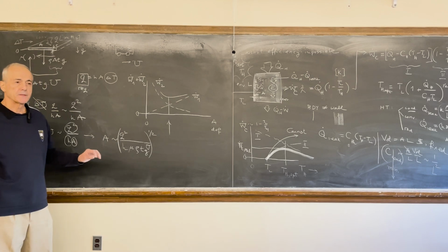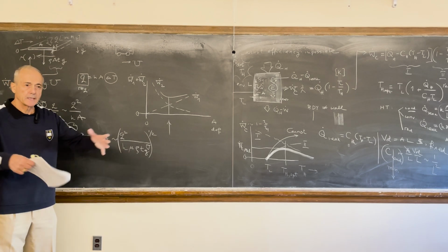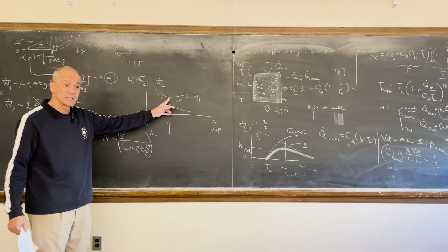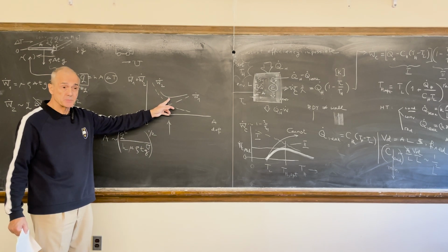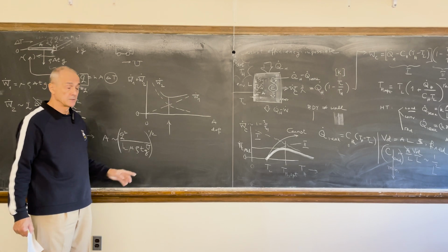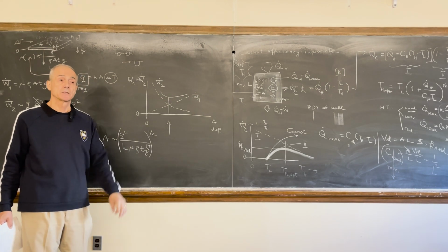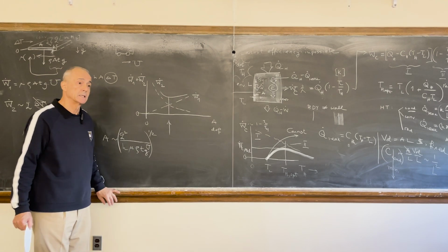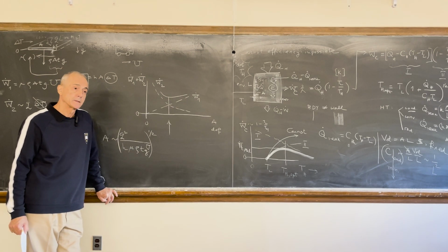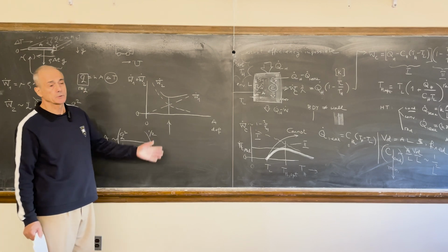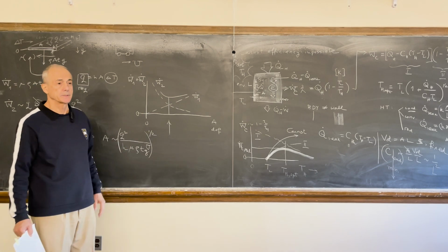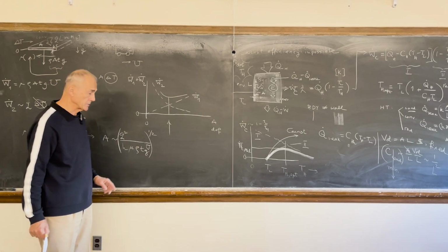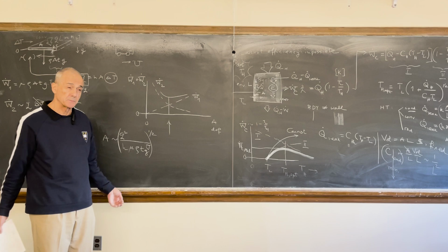In other words, the size of the area for least fuel consumption should be proportional to the heat transfer rate through the surface. So if you hear from the engine maker that the heating rate or the cooling rate to the ambient should be a particular number of watts, you will know that proportional to that number should be the size of this piece of sheet metal.